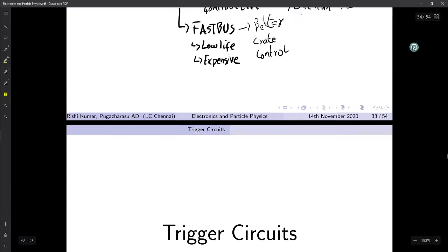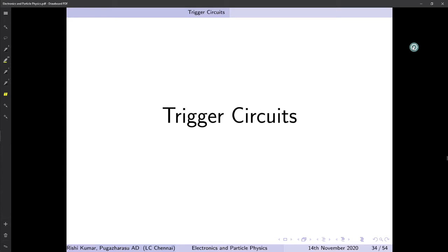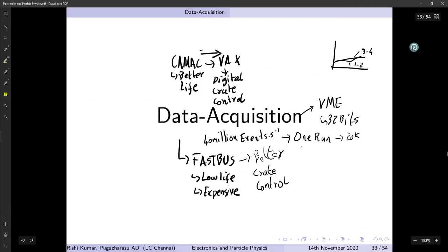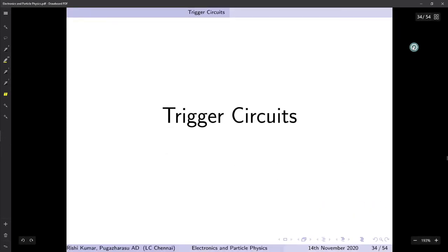And now, armed with all this, we will dive right into trigger circuits and what they are. A trigger circuit is basically the simplest method to suppress useless data and noise. The two greatest enemies to any high energy physics experiment: noise, background noise, and useless data. Because again, remember, 40 million events per second, not useless at all. So triggering is also the first zero suppression, which is to say that when there's a significant interaction, the trigger then signals the larger circuit.